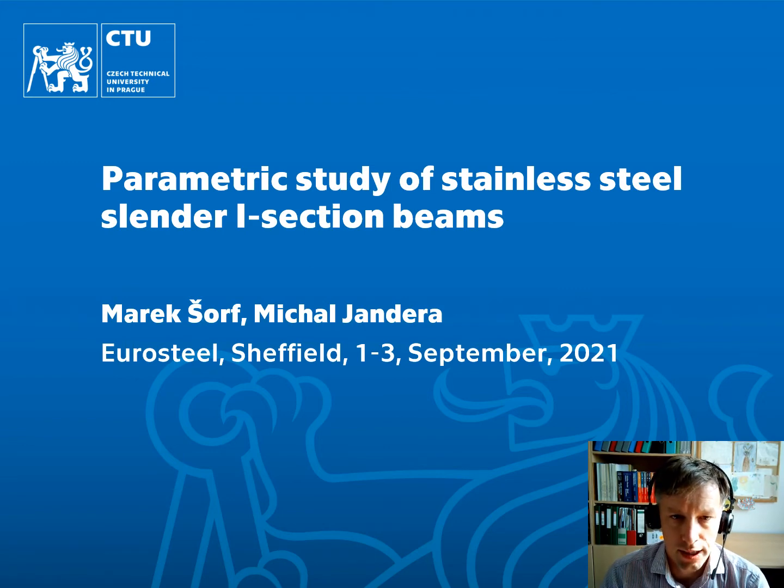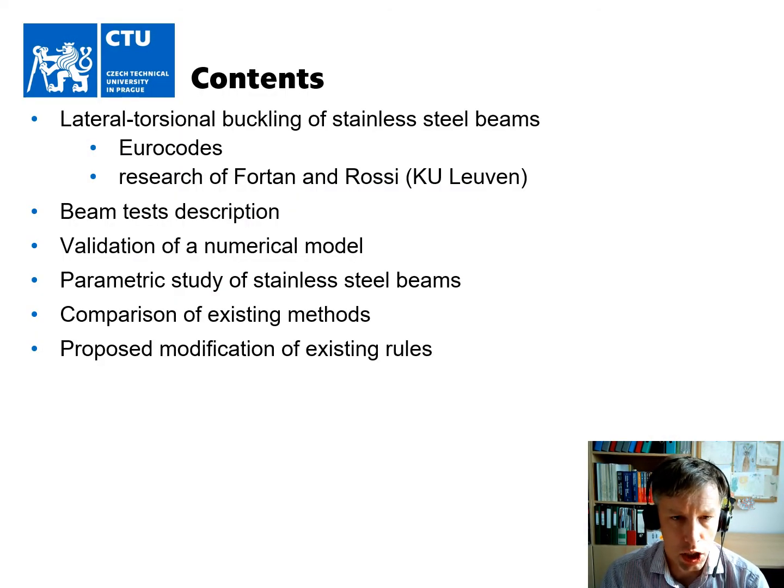I'm from the Czech Technical University in Prague, and I will present a parametric study of stainless steel slender I-section beams, work made mainly by my PhD student, Marek Sorf, so credits to him. I will start with the design rules for stainless steel beams subjected to lateral torsional buckling. I will briefly show our beam tests, a model validation, and a parametric study of stainless steel beams.